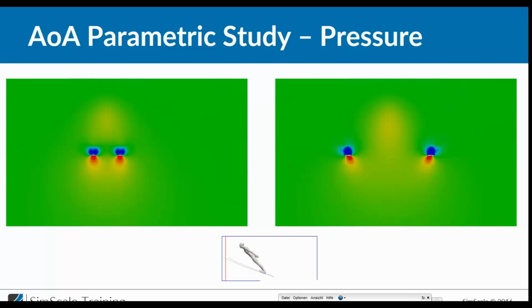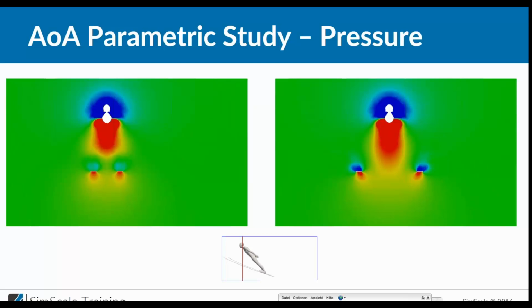Yes, and it's not only the distance, but I think a very important aspect is also the fact that it has an angle. If you take a look, for example, when we have this V angle, the high pressure region below is moved to the center line, while the low pressure region on top is moved away from the center line. And this is related really to the V shape, because we have a change of the geometry, which we'll see better in the next slides, I think. So yeah, exactly. Akram, maybe let's just go through them first of all, and then step by step.